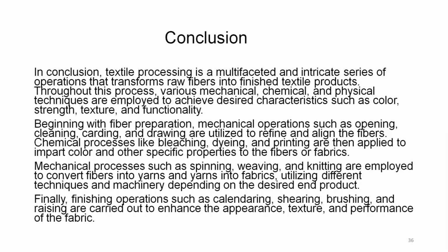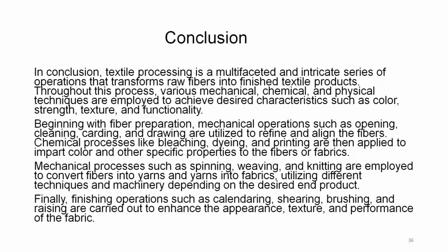And finally, we looked at the finishing operations, because that is how the final fabric is prepared, and the operations such as calendering, shearing, brushing and removal of the fuzz is what is going to make a difference in the appearance, texture and performance of the fabric.